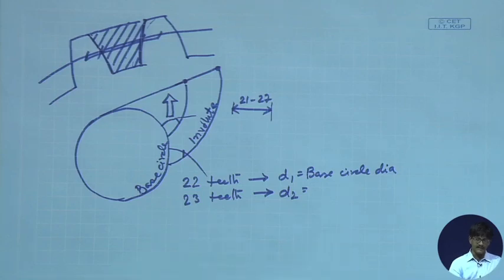Another problem with milling is that you have something called discontinuous indexing. Indexing means turning a gear so that new areas get exposed to cutting action. This is definitely disrupted or discontinuous. You do not cut continuously, you cut and then stop, loosen some bolts, rotate, clamp those bolts once again and then start. Just think of it, there will definitely be some changes in the setting, at least at the micron level.